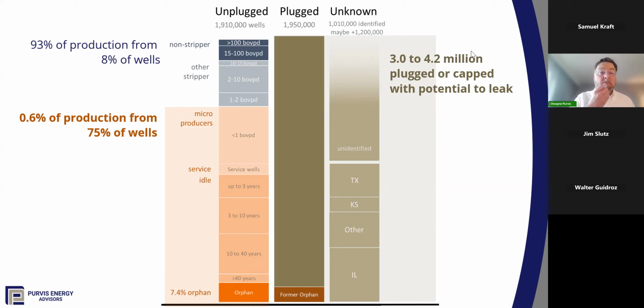There has been some really interesting research on additives to cement, like modified nanopolymers, fly ash to make it a geopolymer, or I recently saw a cement developed under a DARPA grant that was meant to reproduce ancient Roman cement, which has lasted for thousands of years, even under highly corrosive environments. All of those are useful, and it could be better. Probably anything is better than neat Class A cement, which is what we've most often used.